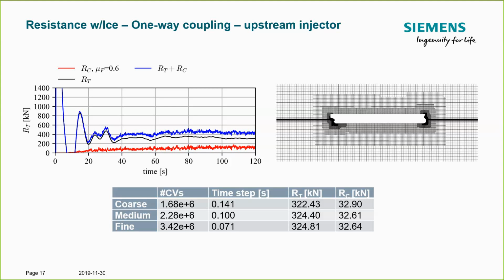So if you run a discretization sensitivity study, which here in that sense means the coarse grid has been refined by a factor of square root of 2 twice to constitute the medium and fine grid, and the time step at each of these refinement steps is refined as well, because this is consistent with keeping the CFL number constant.